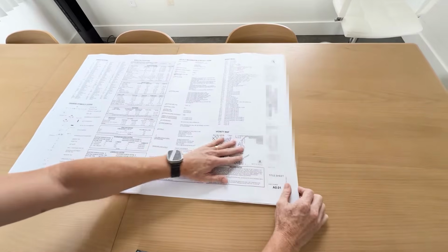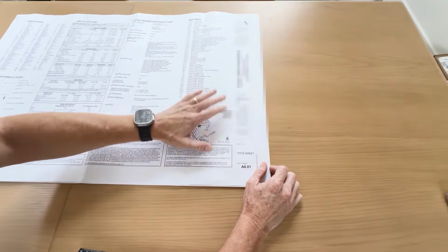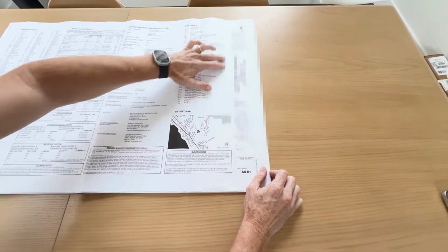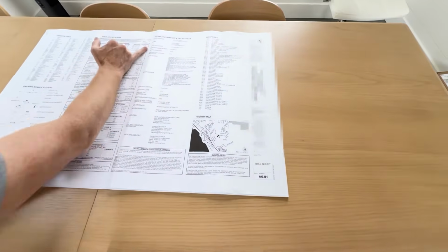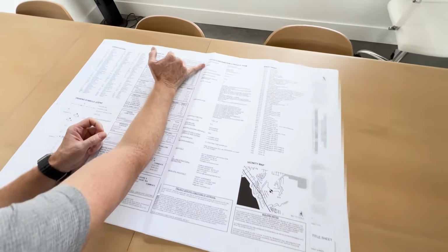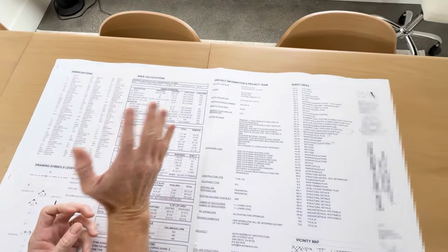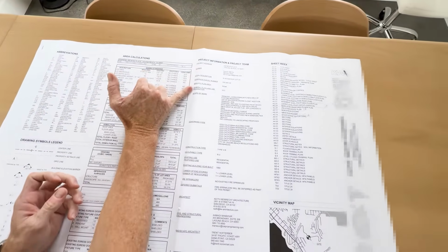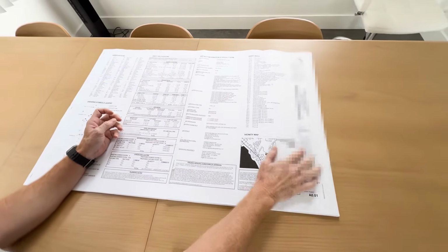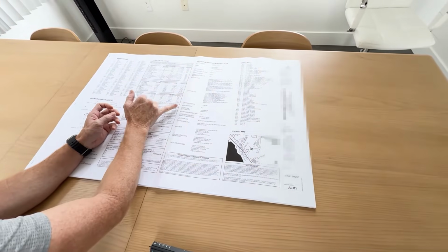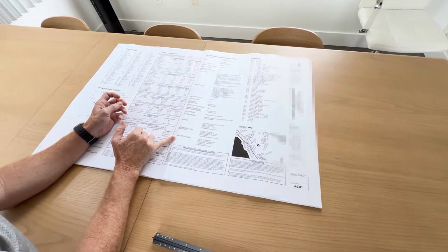Basic building information is usually located right here. We blurred all this out for you guys for privacy, but usually you're going to have your homeowner's name, the architect or whoever designed the project, and just basic notes. As we move across the page, we've got project information, which is more information relating to who's in charge of designing, who's the owner, and any other specialty governing codes applicable for this type of build. You've got your construction type, your occupancy type, and all the way down, a lot more information.